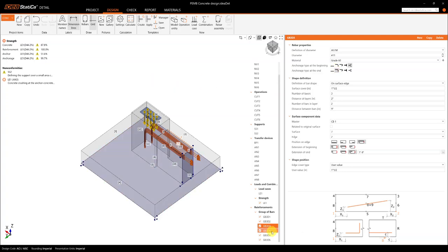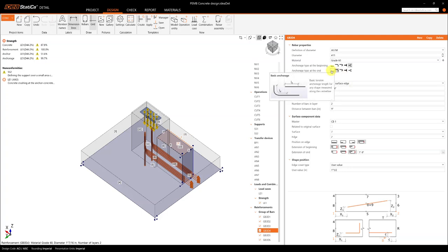Okay. So I did the same in the bottom side to have the other rebar in the bottom side of this beam. Again, this seems messy, but don't worry, this is just a graphical representation. Actually, when you see the results, you won't see these bent parts. You're just going to see a straight bar, but analytically, the bond strength at the end, you will see different values if you select this hook or the free end.